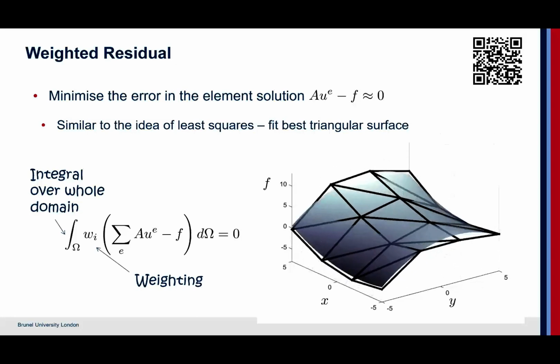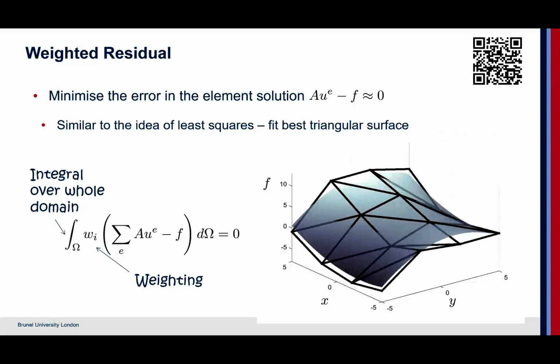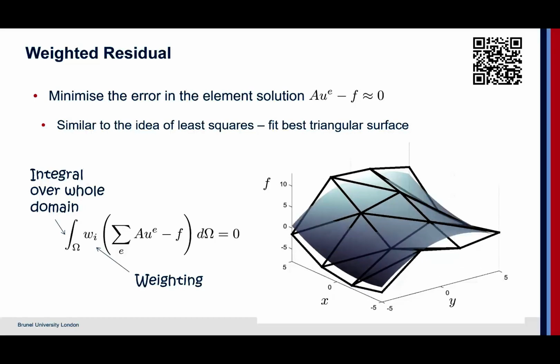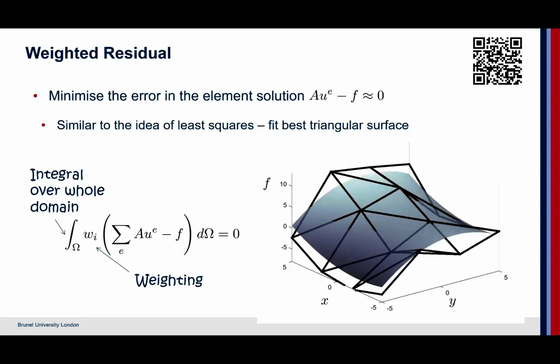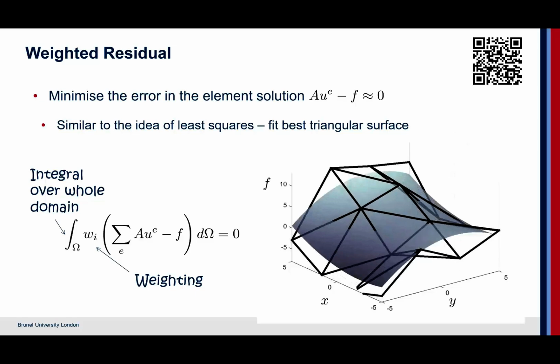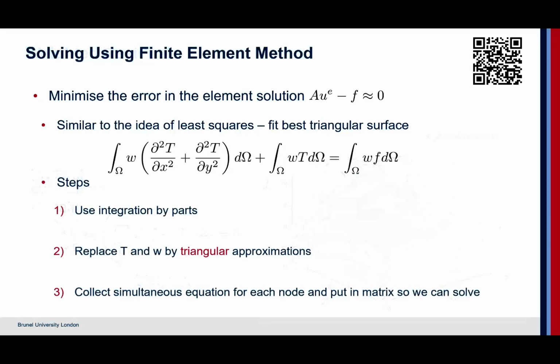solution as possible. So the entire finite element process is one of deriving equations that will get a series of linear or triangular approximations to the underlying function, collect them together into a matrix and solve it. So that's the reason for these equations. So we do that for the equation we want to solve here. We essentially multiply each term by omega, and then we integrate over a volume here in order to get the least squares. Now notice, again, each term is independent and separate here.